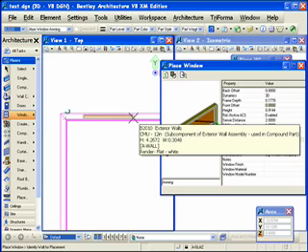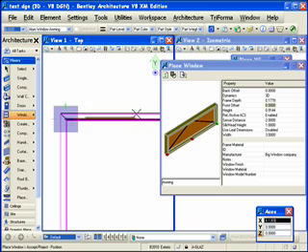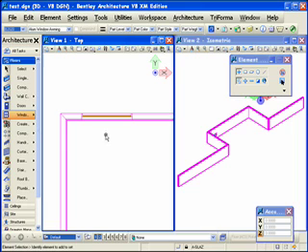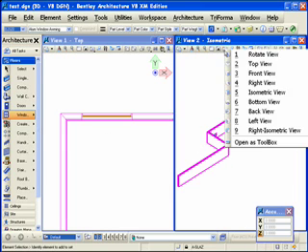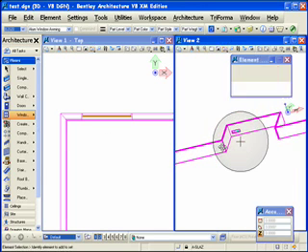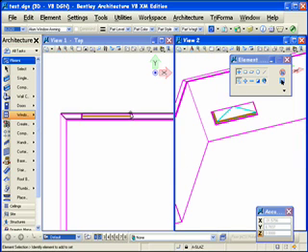This is very handy for doing offsets in walls. And let's place the window. You can see as soon as I click onto or select the wall I want to place it into, it constrains it along that wall. I can now say I want that window right there, and I want it on this side. Thank you very much. And let's just rotate that around for you there. You can see that Bentley Architecture has placed it in the wall, it has cut the hole and placed the object into it, in this case a window.